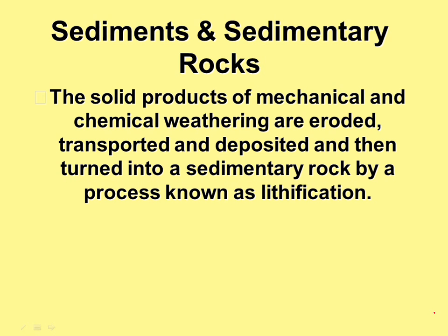As you add more sediment on top of that pile, you generate what's known as a sediment load, and obviously it squeezes that on which it's sitting. It compacts the solid particles, expels water, and reduces the pore space that was originally developed at the time of deposition.